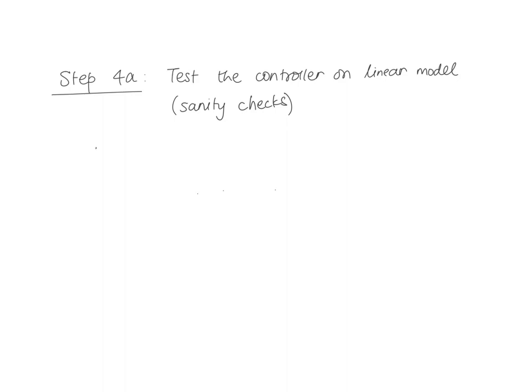For this, I suggest to use Simulink like we did in class. Simulink will allow you to build a block diagram just like the one you saw in the previous 2 slides. So the transfer function a1 divided by s squared minus a2 squared. a1 and a2 are the constants that you are supposed to find out from the linearization.